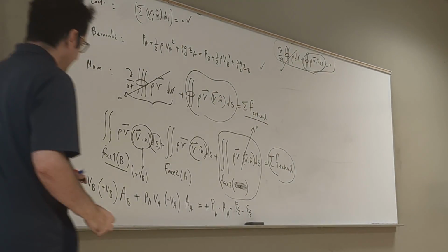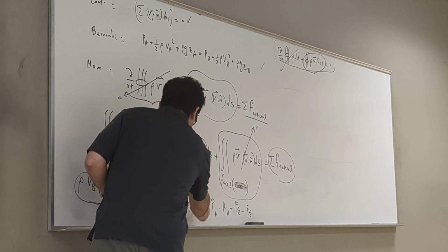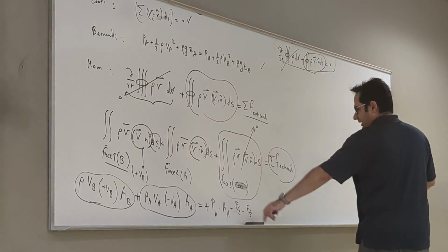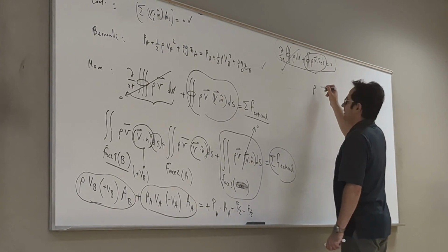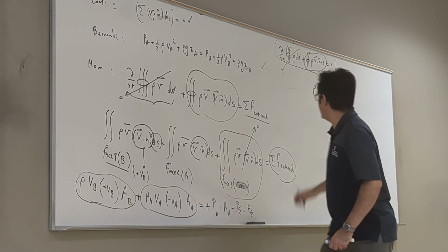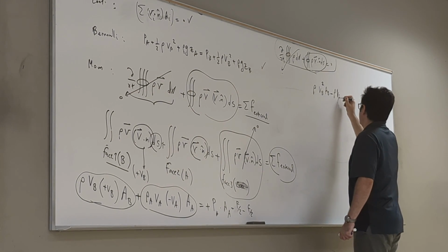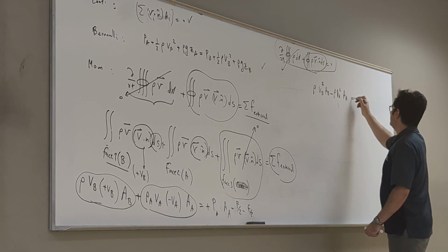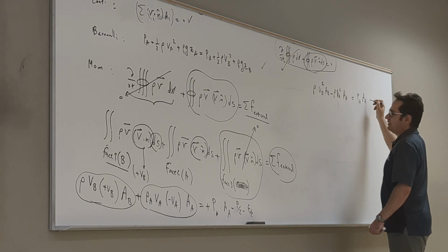Now guys, look at it. These two, you see that? These two are forces. Let me write it here. These two, if you bring everything to one side, what do you get? You get rho VB squared times AB minus rho VA squared times A at A is equal to PA times A at A minus F.